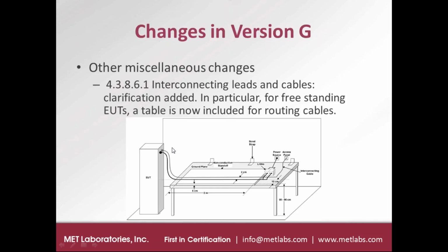In prior versions, you would route the cables from the EUT down to the floor, down to the ground plane on the floor. But now in version G, they require that ground plane to be raised up on a table, just like if you're testing a tabletop device.